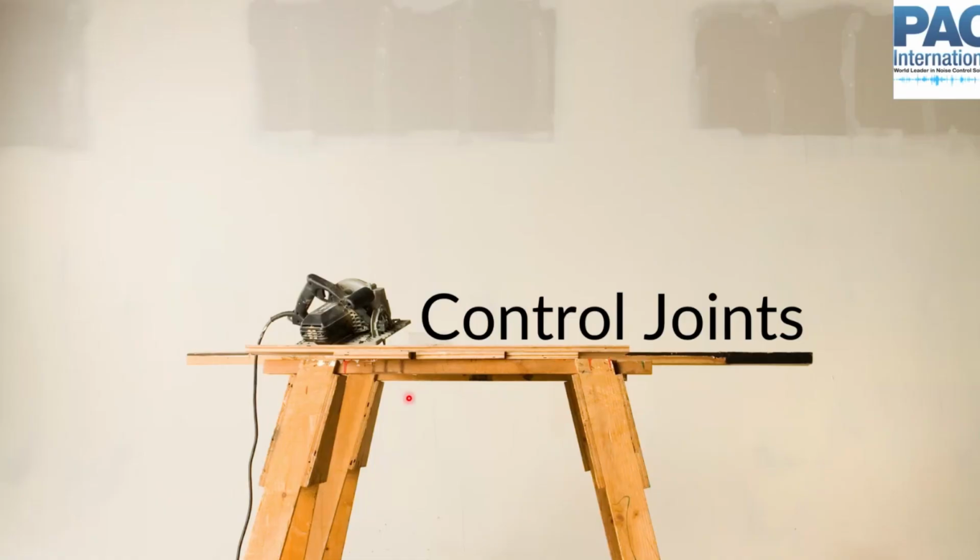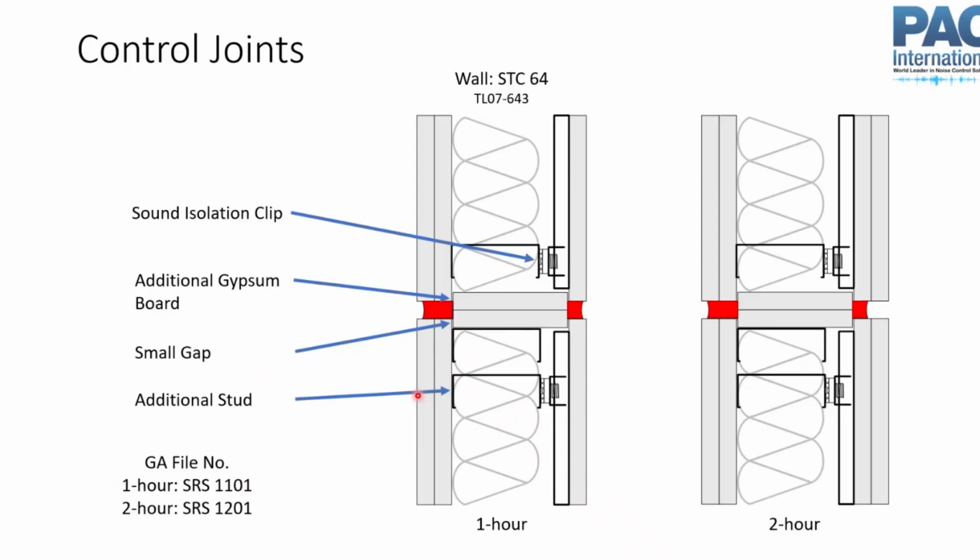Okay, so another instance in a wall where we create a break in our mass layer, our continuous mass barrier, is control joints, right? If we have a long expanse of a drywall wall, we have to put a control joint there to allow for expansion and contraction of the drywall relative to the framing and all of these bits. But that control joint is just a gap. So we need to seal that control joint.